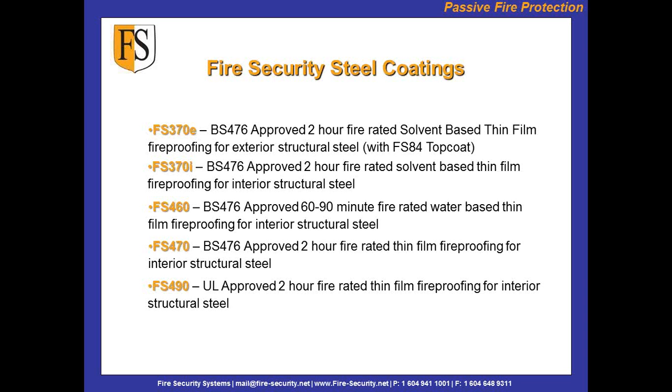Both the 370s are solvent-based fireproofing. No water. Their base is solvent. The base is actually xylene. So if it needs to be cut down, you would add xylene up to 5% maximum dilution.